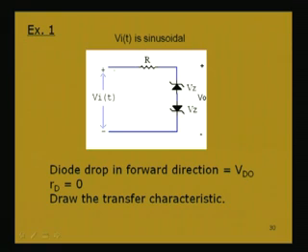So, today we have seen a very important application of normal as well as Zener diodes along with resistance and capacitance to build circuits known as clipper and clamper. These circuits are used in practical applications where we want to use a waveform having one portion clipped off, or clamping the level of the DC voltage of the waveform at some other value than what it is.